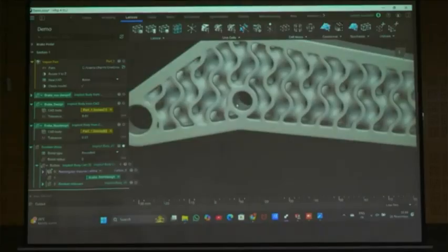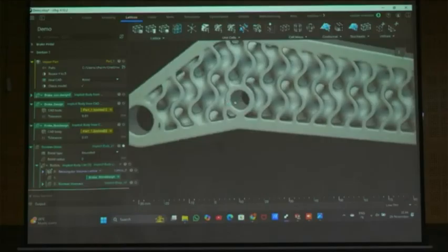Whatever the terminology is, it is the same for both generative and lattice as well as the topology optimization also. The main thing is the preserved region and non-preserved region. Non-preserved means design space and non-design space. These are the non-design space. Always think about it. Holes are the non-design space because that hole has some purpose. We need to put a bolt on it, and we need to do a threading operation. So that should be in the solid format only. That's why we kept it like that. Okay.